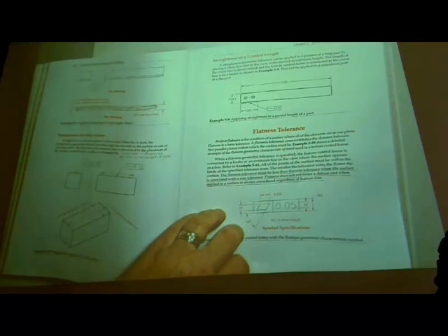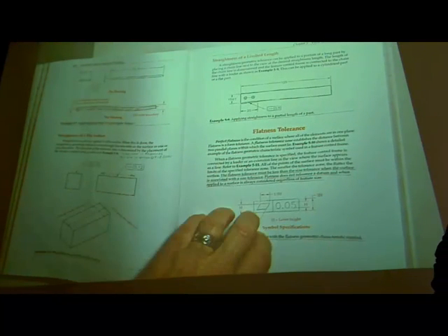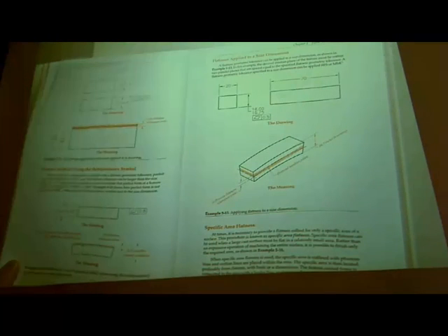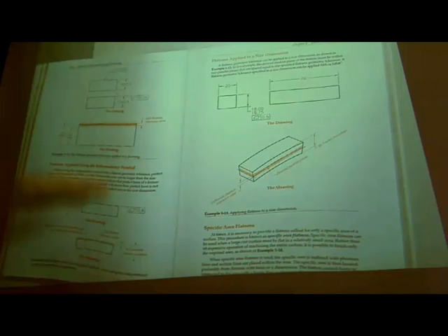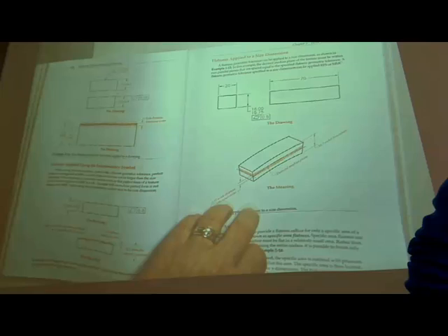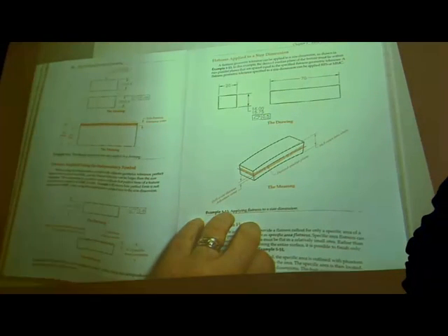We can apply it to a rectangular or prismatic part, flat surface that is. We can apply it as flatness to parallel planes over the whole surface, and it's controlled by the MMC unless we use the independency symbol.